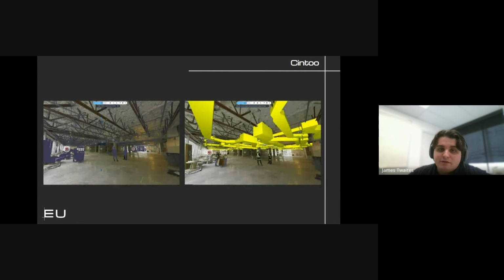And one of those examples would be, this is Syn2. This is a platform that outsources the computing for that to their server so that anyone can view the point cloud in a browser, overlay models with it, and compare it to the design. And ideally, that means that everyone has access to it with a much lower barrier to entry right from the beginning. On the right there, what you see in yellow, that's the duct layout according to the mechanical engineer's